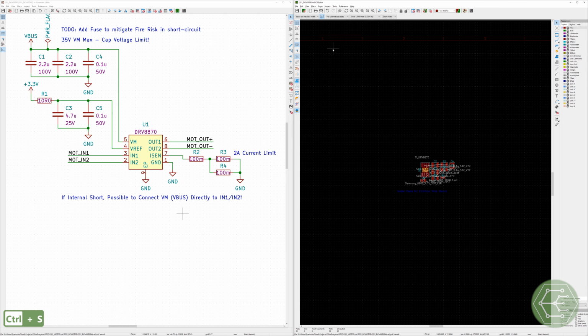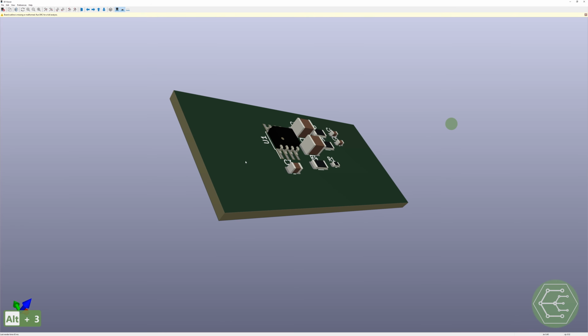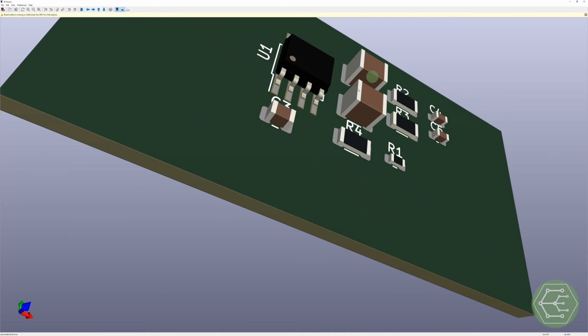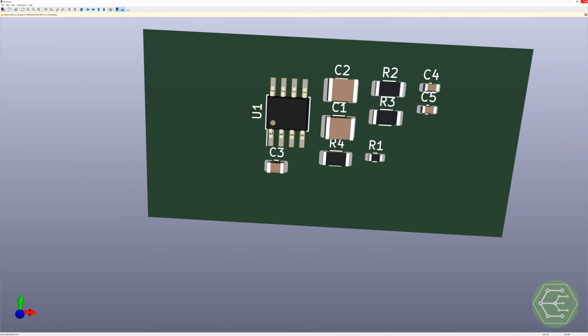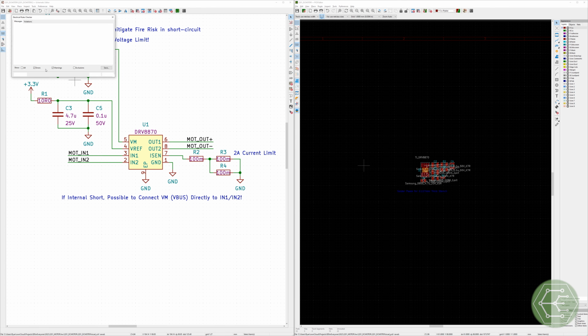We can see the 3D preview. Looks beautiful. Pin 1 indicators all around, silk screen surrounds. Phenomenal. Pulled in those parts. If we run the DRC here, we'll get some errors about 1-pin nets.